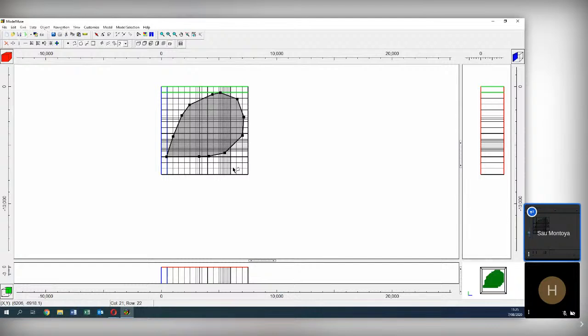Why will it be inactive? Because it is not in the active part of the hydrogeological basin. So you will have this part active and this part inactive. But then you are wasting cells, because these inactive cells are still part of your model construction. You won't compute them, but they will be in the matrix as inactive.